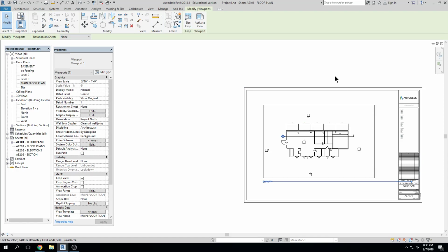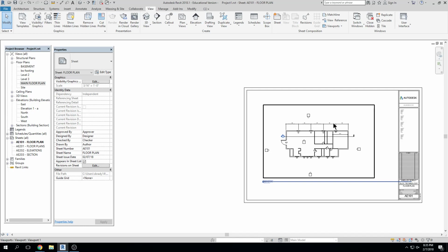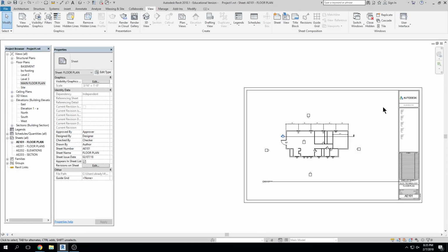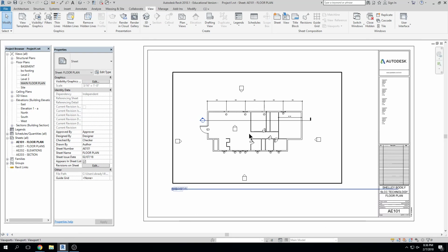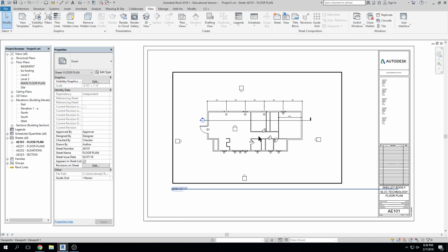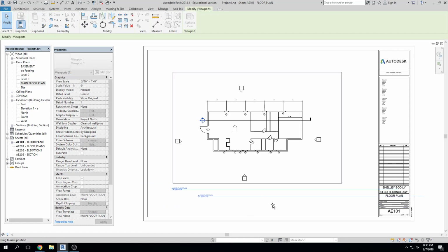I click on it, I can move it, I double click, click, I engage it, I click, click, I disengage, okay? If I click, click, and engage, and then I want to disengage again, I can also right click and choose deactivate view, right? So there's a couple ways I can activate or deactivate this. Okay, so now if I want to change the view title, this is called a view title down here. If I just, without touching the viewport, if I click on that line, I'm able to move this viewport around.